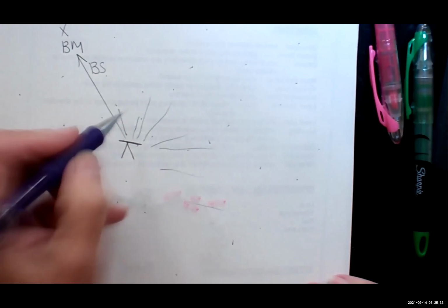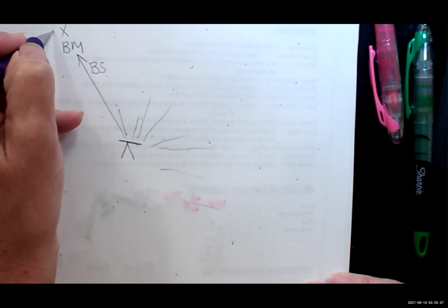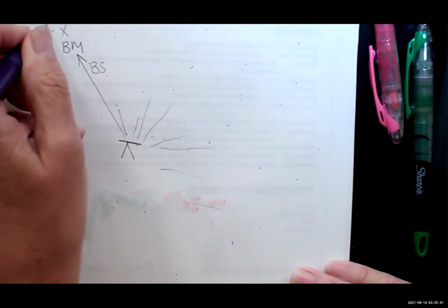The only thing is you have to be careful, right? What if you kick the instrument? What if you kick the legs? What if a kid comes by and kicks the legs? You never know, and you don't know if it's moving either, right? You want to check yourself as you go. So what you might do is shoot five and then shoot the backside again to make sure that you get the right value. Then shoot another five, shoot the backside, and then shoot another five and shoot the benchmark again.